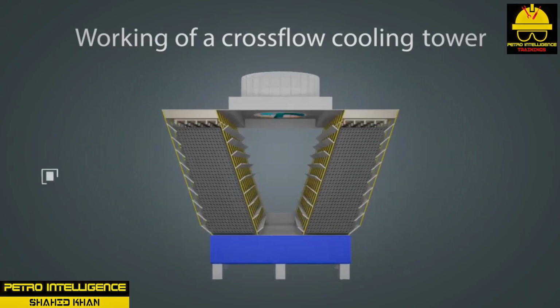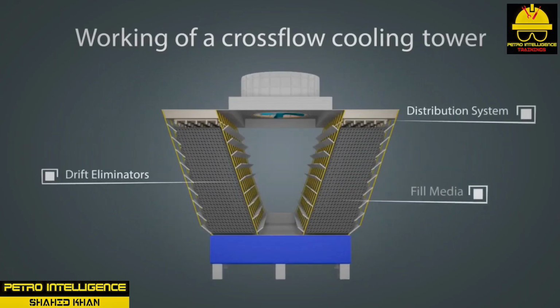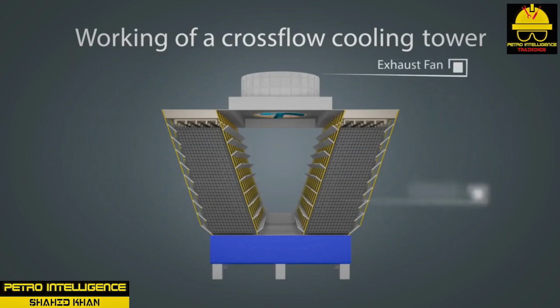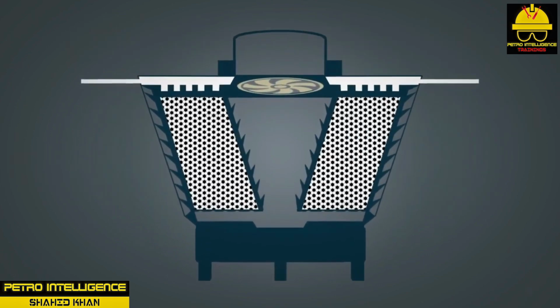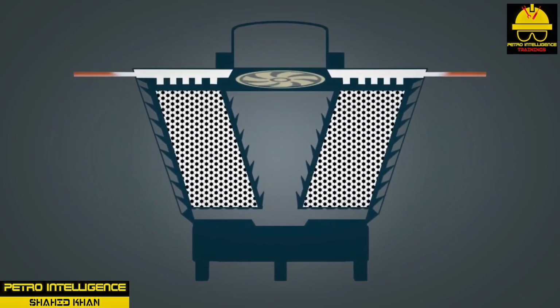Temperatures in a cooling tower are closely controlled. The temperature difference, delta T, between the inlet air temperature, wet bulb, and the outlet water temperature is referred to as the approach to tower. The temperature difference between the hot and cold water is referred to as the cooling range. Cooling tower capacity is defined as the amount of water a cooling tower can cool.